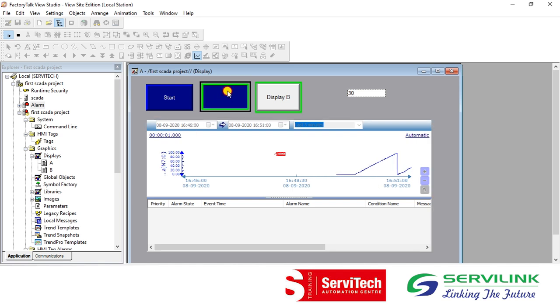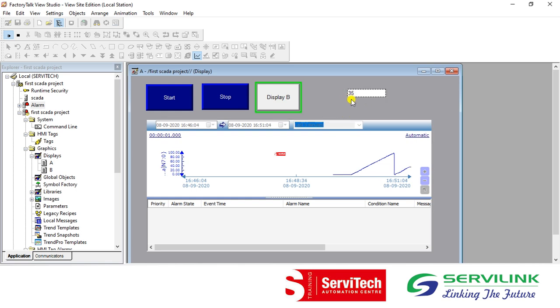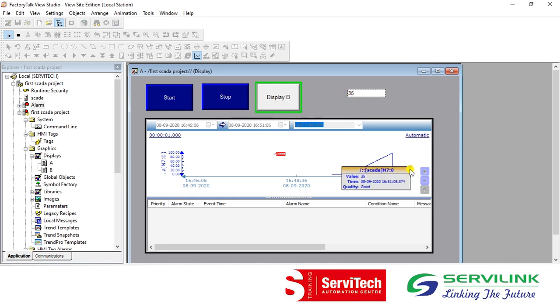And if I stop the process, the value of that particular integer address is 35, so it will draw a straight line. So whatever data is coming from the PLC, that data will be displayed in this graph. Like this we can configure a trend in our SCADA software.